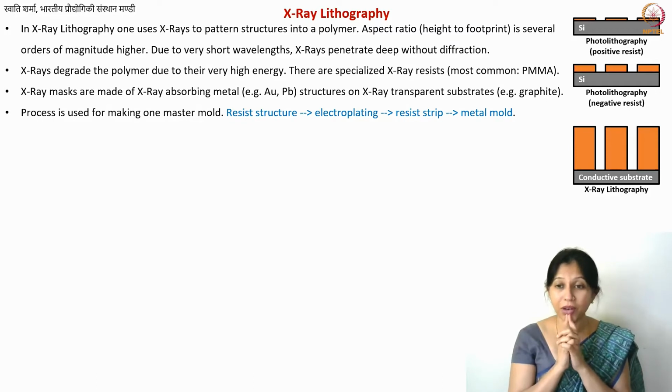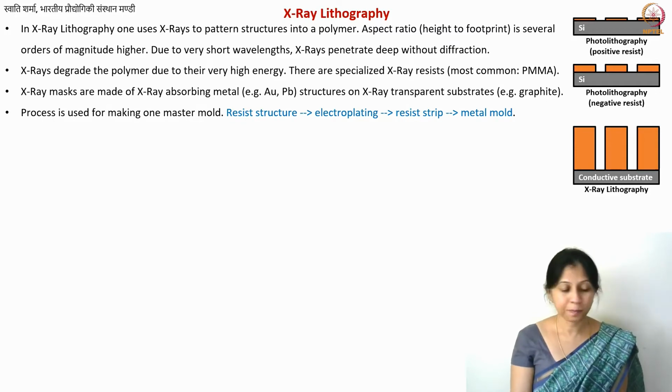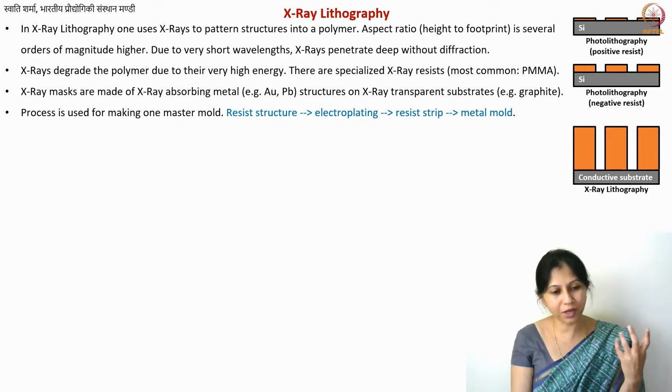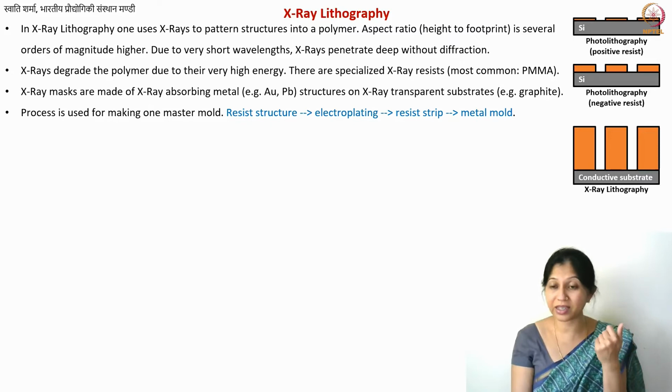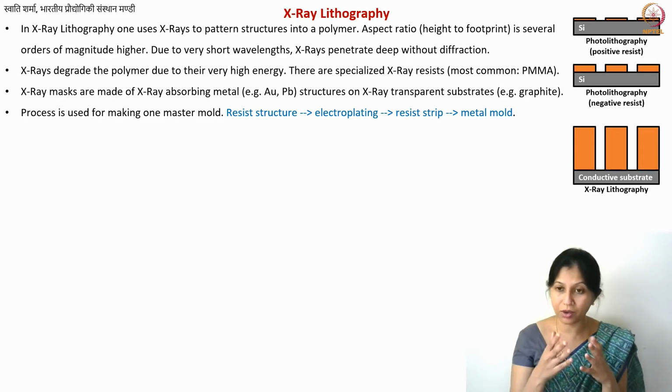Now, why is the mold fabrication done? X-rays are very expensive, and the X-ray lithography process is also relatively expensive because you do not have these facilities everywhere. X-ray generation facilities are not available everywhere, and they require a lot of safety features. Also the masks are very expensive, which is one of the biggest factors that adds to the cost. So altogether, X-ray lithography is very expensive.